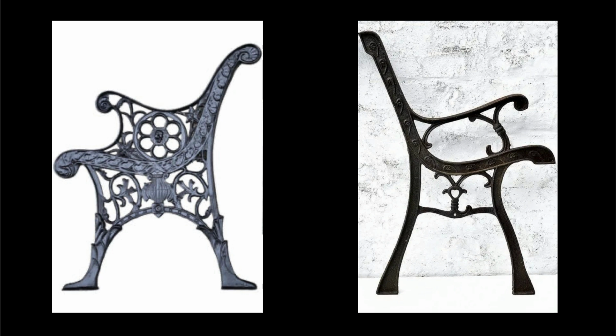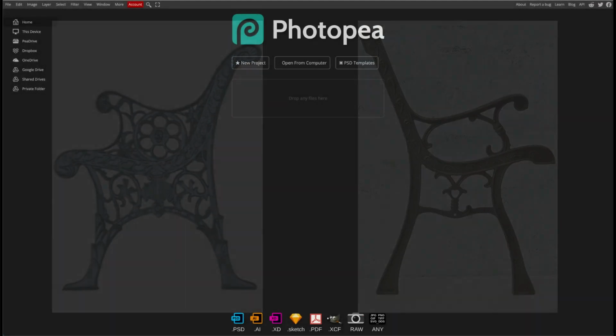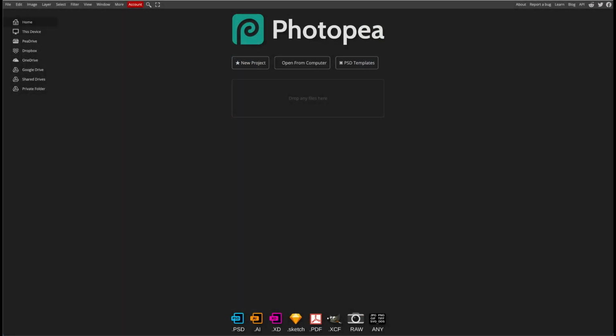One could start with a single vertex and extrude to copy the outline, although this would be somewhat tedious. Fortunately, there is another way. One can use an image vectorizing program to convert the image to an SVG file that can then be imported into Blender.